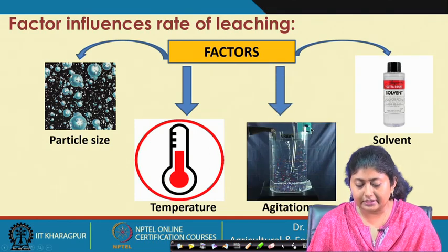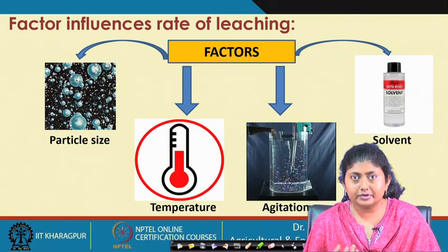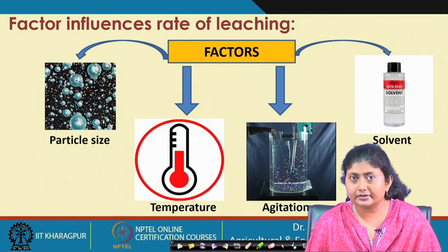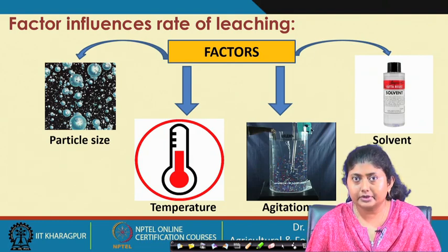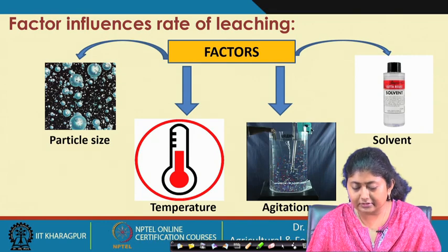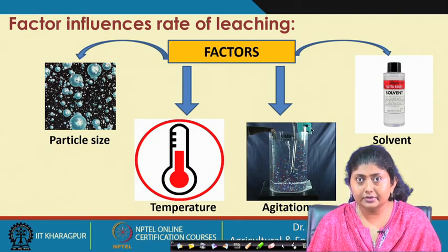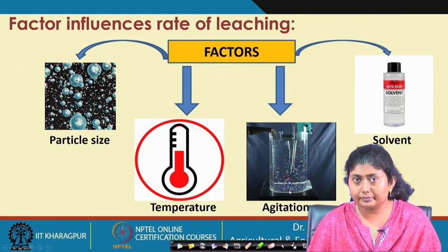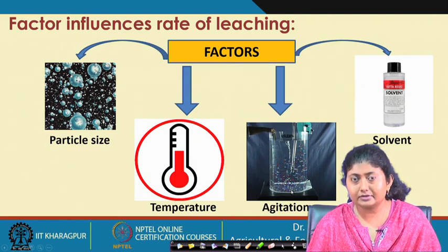Now, agitation. Suppose the micelle is there, the particles are there, and the solvent is coming into contact with them and extraction is taking place. All the processes of diffusion, dissolution and then bulk transfer are very slow unless you provide mechanical agitation to it. Okay. So, if agitation is given in a system, definitely extraction will be very fast, because then the portion of the material which is normally exposed to the solvent will be enhanced by this agitation.